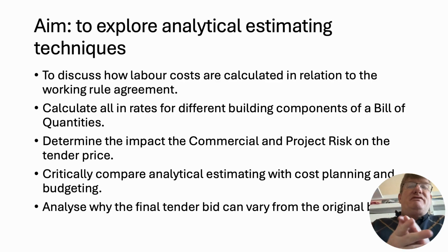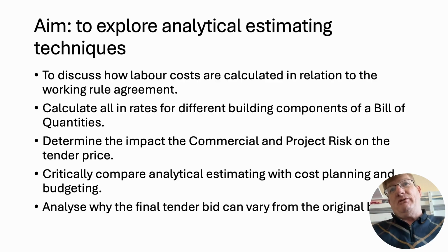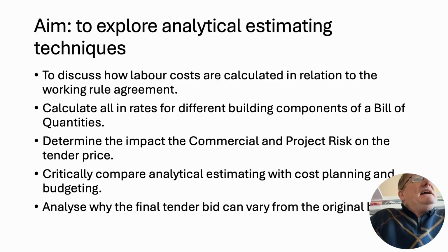You need more information to do that, because you'd start off with your cost estimate based on a gross floor area or a functional floor area, following all the rules listed in NRM1. Then when you've got more drawings, a more detailed specification, and health and safety information with regards to CDM, so maybe a health and safety report, you can start to produce much more accurate quantities.